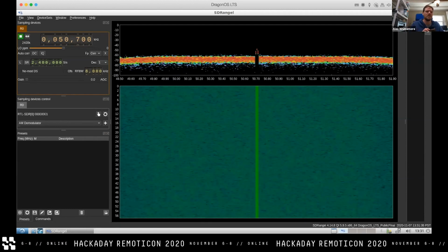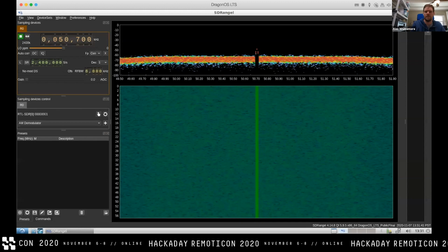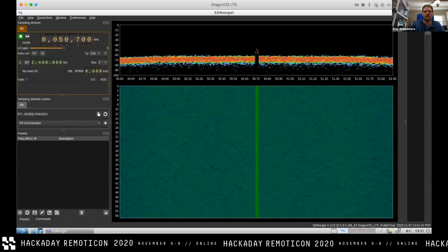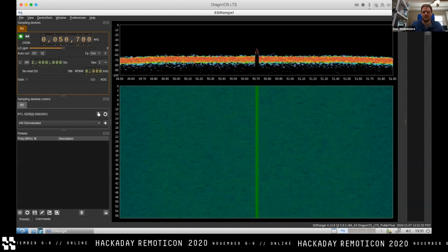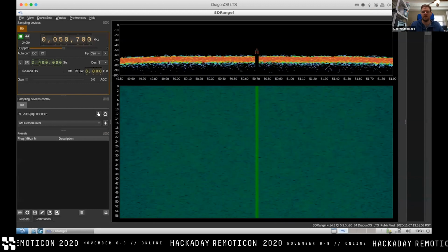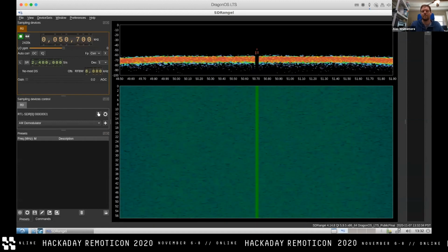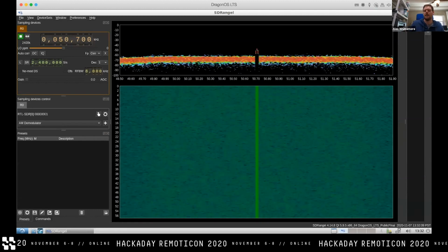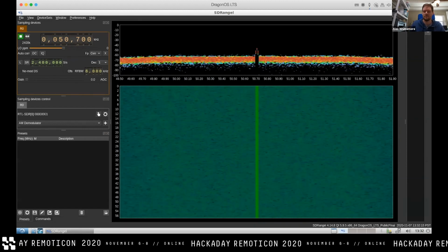So this covers basically the entire practical RF testing regime from 30 megahertz to 1 gigahertz, and then from 1 gigahertz, technically the higher range is 1 gigahertz to like 13 gigahertz, but at least in my experience, just ignore it if it's too high, because you probably don't want to spend $30,000 a month on a 13 gigahertz spectrum analyzer. And if you do, at that point, $500 an hour for your RF testing facility is like, okay, fine, we'll suffer it. Your product probably doesn't have any violations that high unless you're trying really, really hard. At least in my experience, which is limited. Yours might be better.